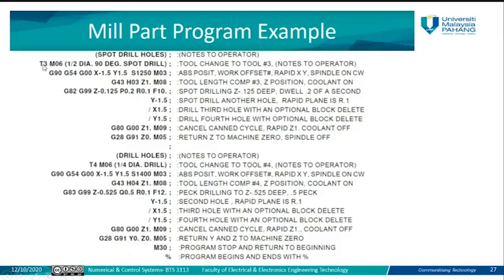Then we go to tool 3, we change to tool number 3, and the comment here is stop for drilling. So this is a tool change to tool 3, not to the operator. In this case, if you want to change the tool, you have to stop the machine first, then run the machine again.